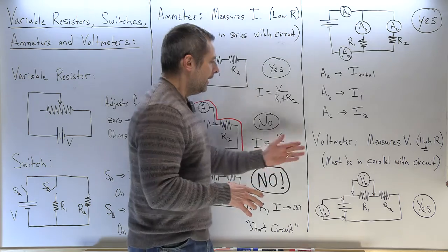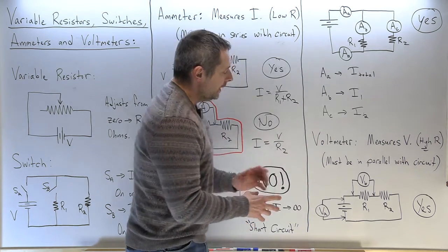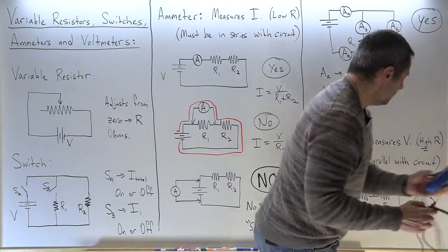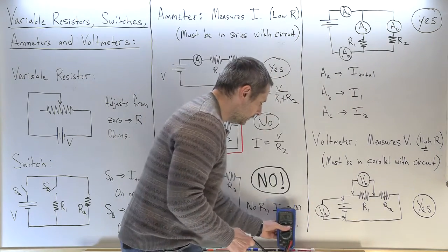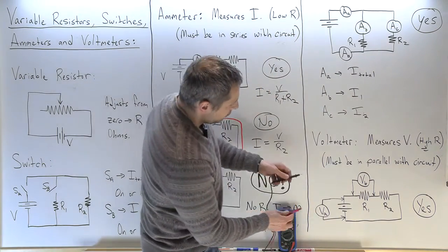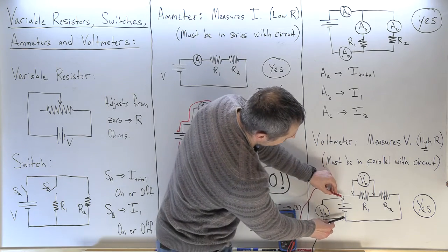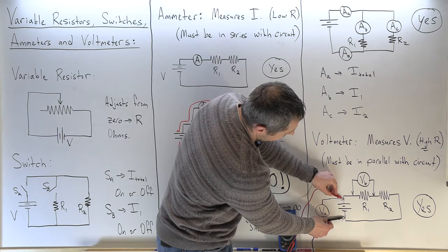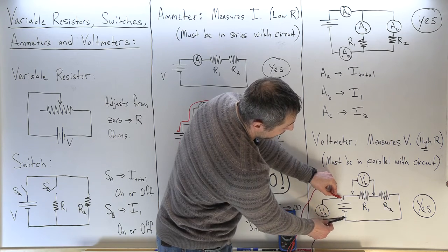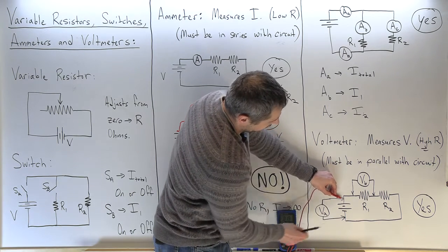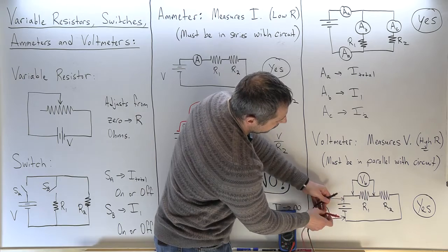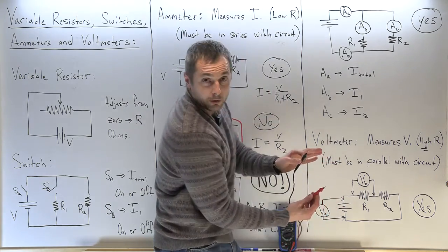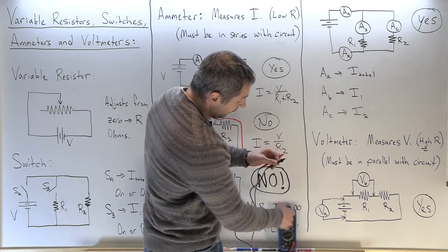All right, so the voltmeter there, I already explained. This is how we would connect the voltmeter in a circuit. One possibility is I take these probe wires and put them on either side of the voltage source. Red is to the positive, and maybe this is a 9-volt battery, and then it would read 9 volts on this screen. By the way, if I switch these, it would just read negative 9 volts because the voltage would be backwards according to the polarity of the meter.